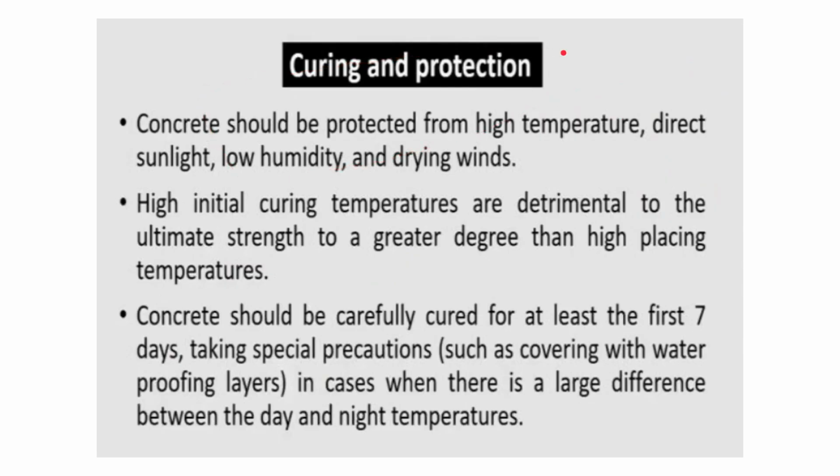Apart from them, let us see the curing and protection stage. Concrete should be protected from high temperature, direct sunlight, low humidity and drying winds, as we studied just now. High initial curing temperatures are detrimental, because they result in an increase of thermal cracks, affecting the ultimate strength to a greater degree than high placing temperatures.